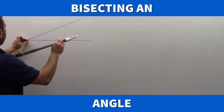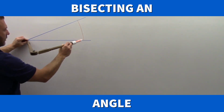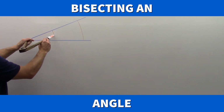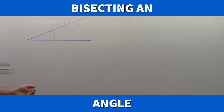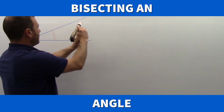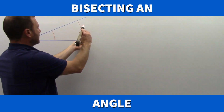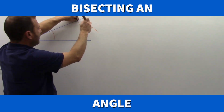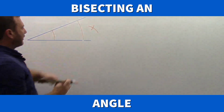what I'm going to do is take my compass and swing the arc that encompasses that angle. Doesn't matter where it is, it could be anywhere along that angle. Just something reasonable and something not too small, not too big. And then we're going to bisect the arc. So again, I have a point at the one end. I don't need to go through the bottom side, but I go approximately 3/4 of the distance. I swing to the outside from one end of the arc and from the other end.